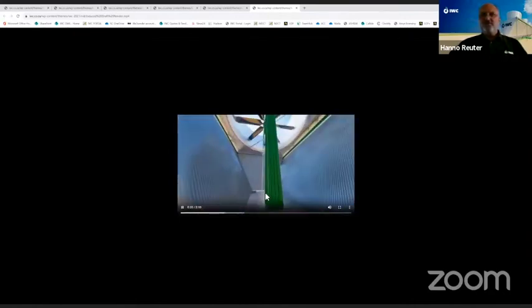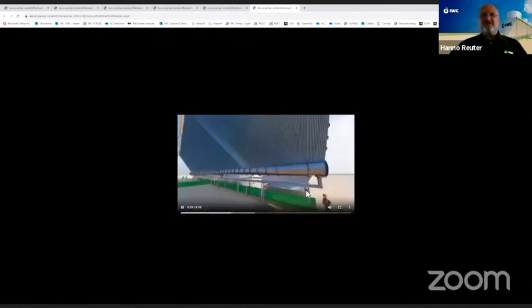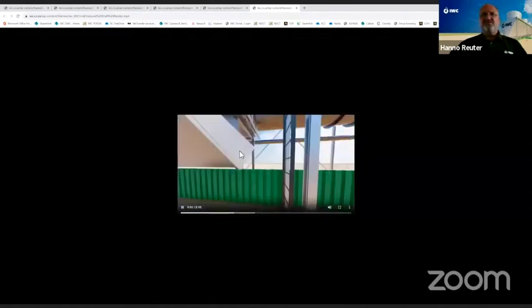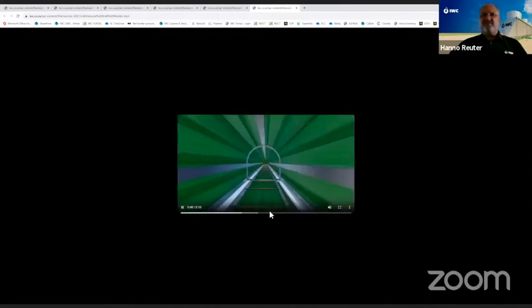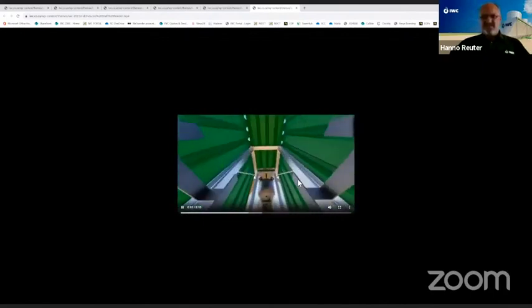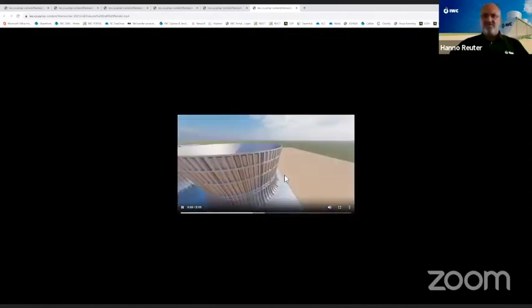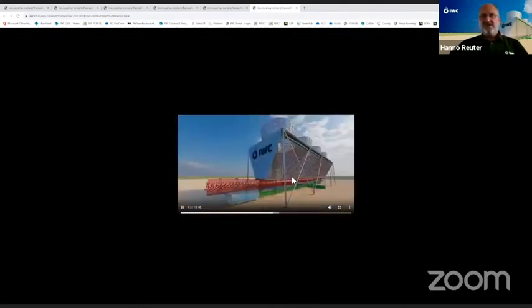So here you see in the floor, you see these gratings, so to speak. This is where we put in a booster system called the hybrid deflegmator, and you'll see it underneath. I'll tell you the details just now. This is incorporated into the air-cooled condenser, and it has the impact of a supercharger for the air-cooled condenser. So it's an evaporative system to enhance the performance dramatically. Then also our system has a fan stack with a diffuser, which allows for improved fan efficiency, all enhancing performance. So here you see the streamlines as the air flows through the system.